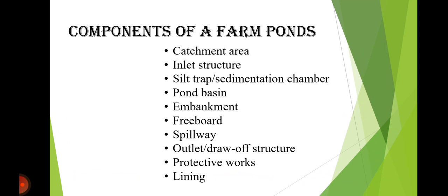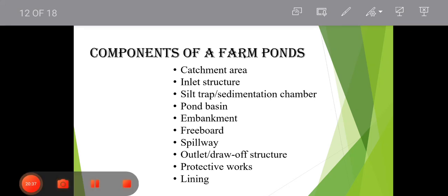So what are the materials used for the lining? Clay, concrete, brick masonry, plastic membrane. In plastic membrane, HDPE and PVC material is used. The function is it minimizes the seepage losses and improves the water use efficiency.